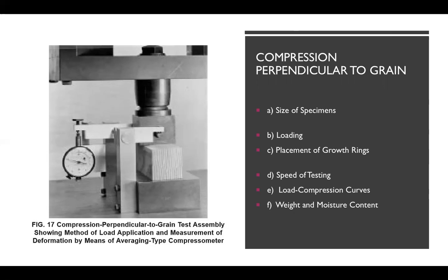load compression curves shall be taken for all the specimens up to 0.1 inches or 2.5 millimeter compression, after which the test shall be discontinued. The deflection reading shall be taken to 0.0001 inches or 0.002 millimeter. And